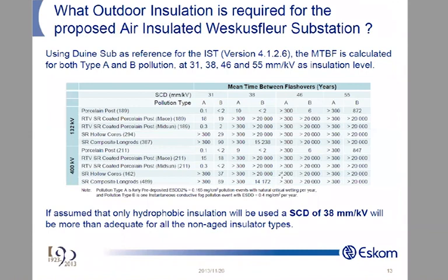So now what happens is, for dew to fall on that RTV coated porcelain is more difficult than it is on the normal bare silicone one, because of this temperature retaining. But also, you normally have in your coating or in your insulator itself, alumina trihydrate. Alumina trihydrate is actually water molecules which can become available. Aluminium, okay, with OHs, and then when they break off, they become water molecules, and then the arc heat is transferred into the water molecule and it explodes, and as it explodes, it shifts the arc, and that's how you get arc resistance.